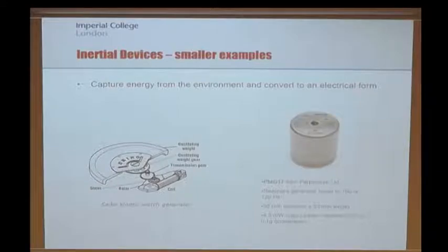Essentially, if you take the back off one, you see this mechanism. The face of the watch obviously is circular, and the inertial mass in the device is this half circle, connected to a generator here through a high ratio gear train. So you move this mass a little bit and you get very fast motion of the generator itself. As you tip your wrist from one side to another, this swings around and generates electrical power. It's generating a few microwatts typically, and that's all you need for a watch.